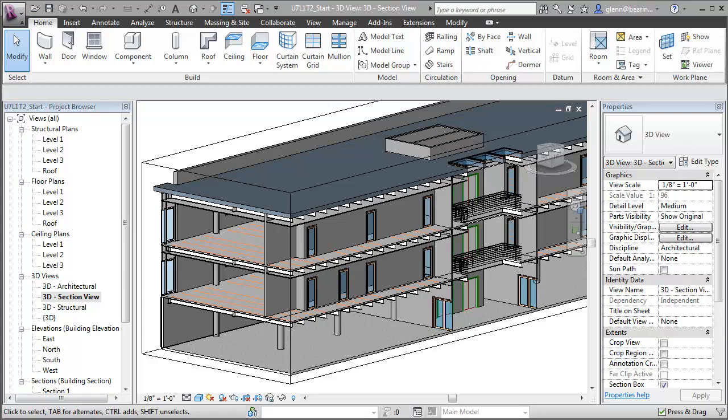to a significant difference. To make it easier to address both these needs, Revit 2012 introduced a new feature called Parts, which lets us break down multi-layer assemblies into individual parts so that we can edit, schedule, and work with them independently, while still adopting the changes made to the original element. Let's move to a simpler model where it'll be easier to see the effects of working with parts.